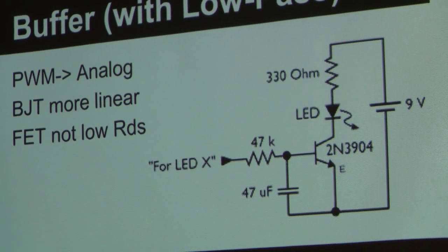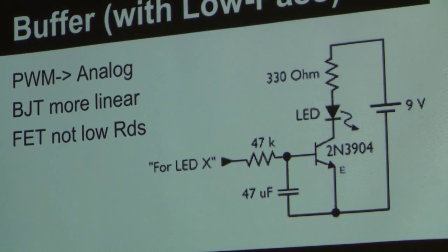Yes? The other thing that you pointed out is that despite being a voltage device, while it's charging that gate capacitor, the FET is consuming current while it's getting switched on. Yeah. I'm going to touch on that for just a little bit for the FETs. But the FETs depend on that voltage getting them down into a low current range.